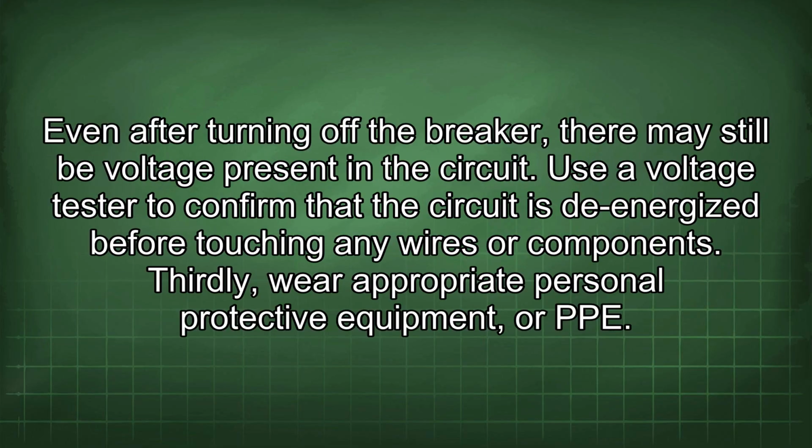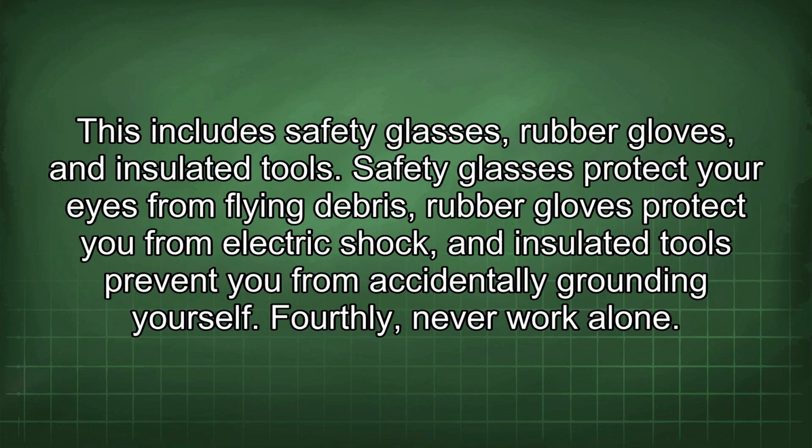Even after turning off the breaker, there may still be voltage present in the circuit. Use a voltage tester to confirm that the circuit is de-energized before touching any wires or components. Thirdly, wear appropriate personal protective equipment, or PPE. This includes safety glasses, rubber gloves, and insulated tools.